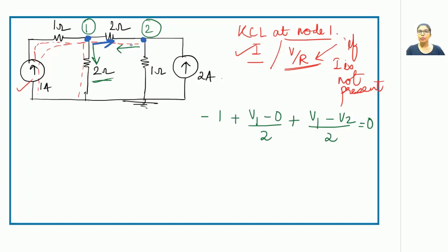In case you are making some mistake, like while considering this node voltage 2, you are assuming that the direction of the branch current for this particular path is from left to right, then you are actually bringing a wrong concept into the picture. So the underlying principle is, no matter whichever node you are considering, the current should flow in the outward direction. Based on this concept, let us write down the equation at point 2 or at node 2. What will be our equation?